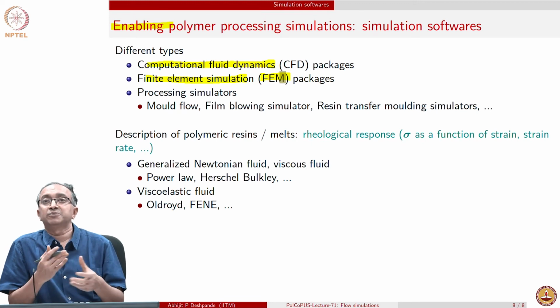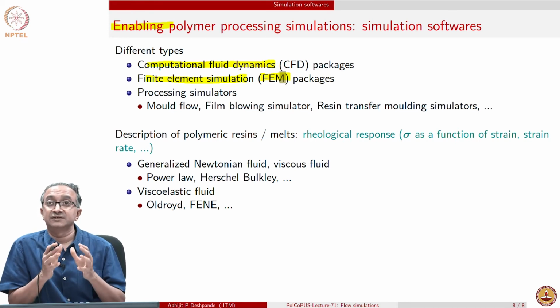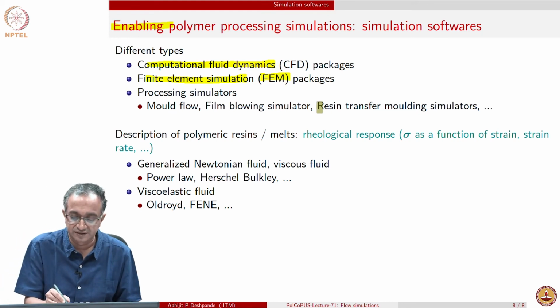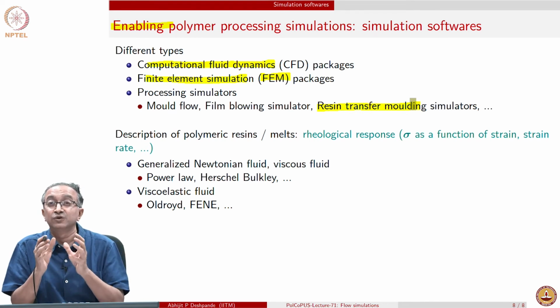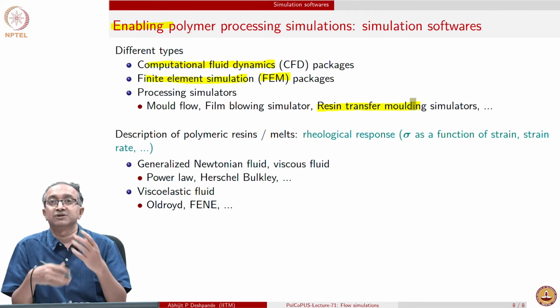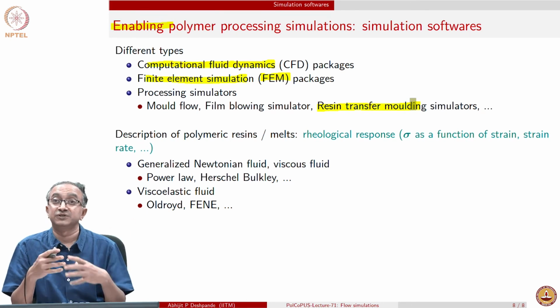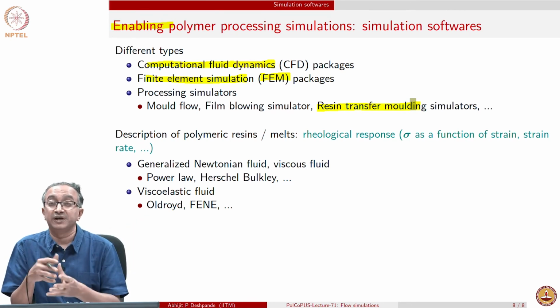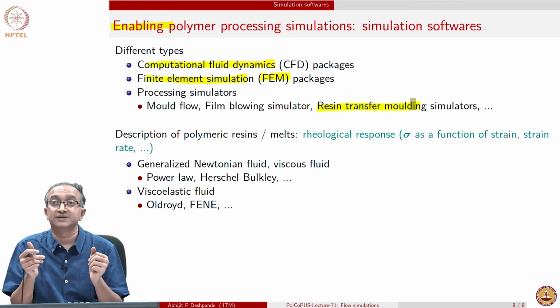You can solve any problem by suitably defining that problem in the overall software. However, there are trade based simulators also. So, for example, if a company is using only resin transfer molding, then there are simulators available which can quickly give you again assessment of what flow rate to use, what pressure to use, or what could be the viscosity which is appropriate for having a nice spreading throughout the fibrous bed in case of resin transfer molding.